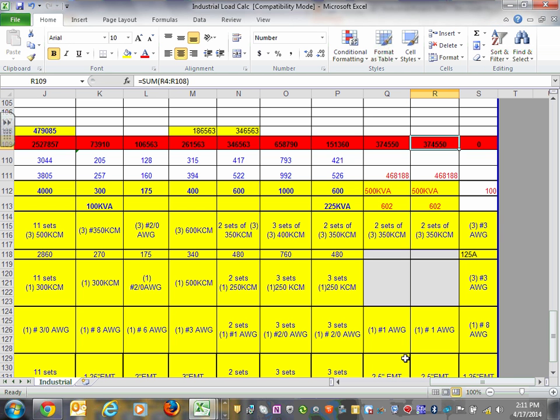After I came up with the 4,000 amp switchgear, guys, I could sit there. Utilities do that all the time. And say, you know what, every single building of this type we sized, we put a 3,000 amp switchgear for your switchboard. What makes this different? So I can go sign off on it and make it 3,000 as a professional engineer. You as a master, you can do that, but you're taking liability if something happens or whatever. So I like what